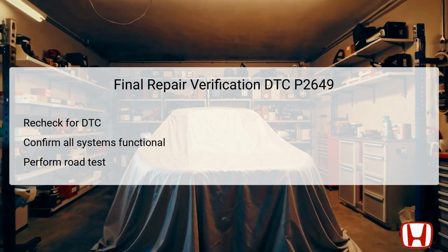For final verification after completing repairs related to DTC P2649, it's crucial to recheck for any DTC codes using the HDS. Begin by starting the vehicle and allowing it to reach normal operating conditions. After this, scan the system for new or recurring DTCs to ensure that the previously indicated DTC P2649 has been resolved. Confirm that all systems, particularly those involving the VTEC system and rocker arm oil control, are functioning correctly without